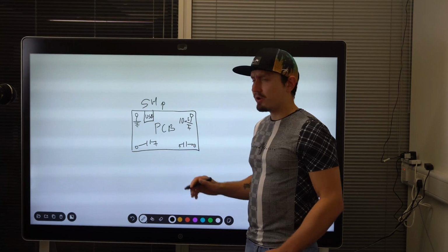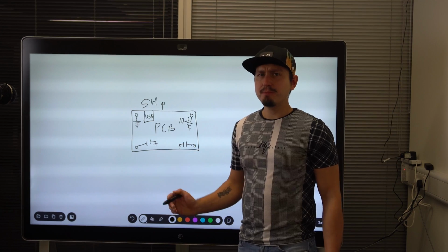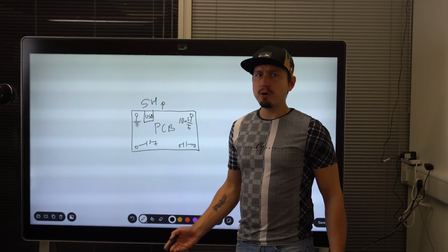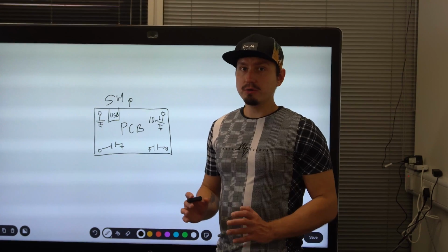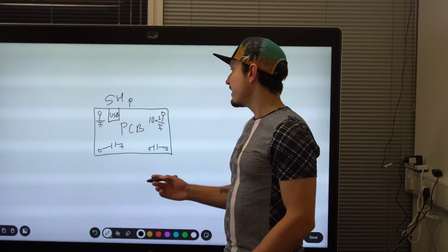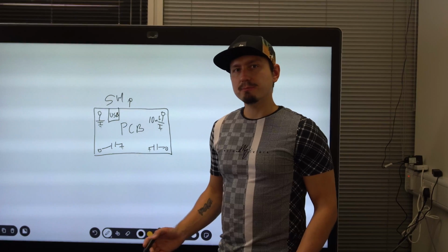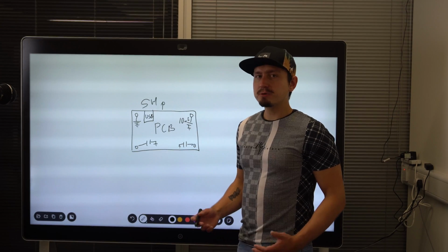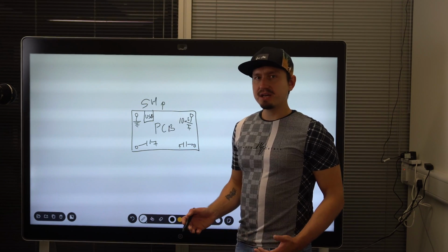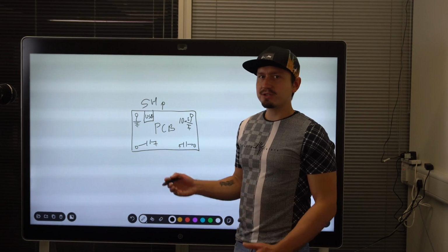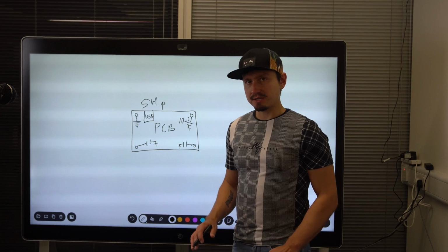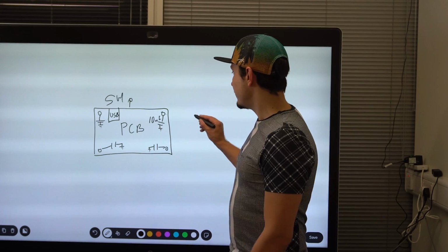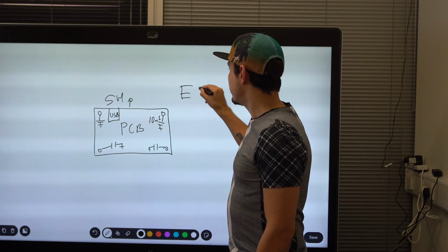What this makes sure is that we have a high frequency path for the current to flow, and that lowers the impedance of our ground plane because it is now connected to the chassis in multiple points. So that helps to dissipate ESD currents when we have electrostatic discharge applied to the unit into the chassis. So this is extremely important for ESD as well.